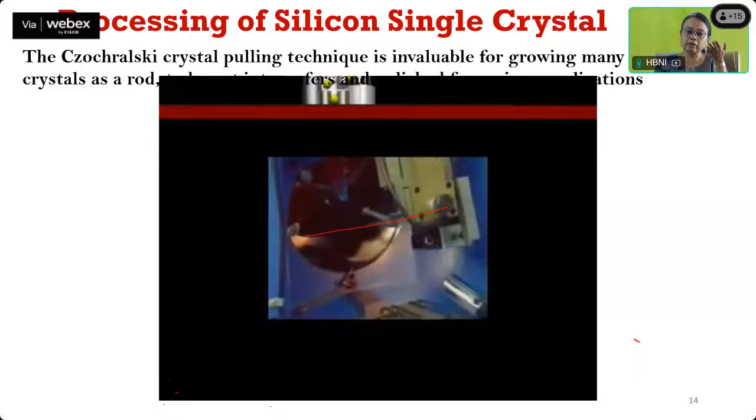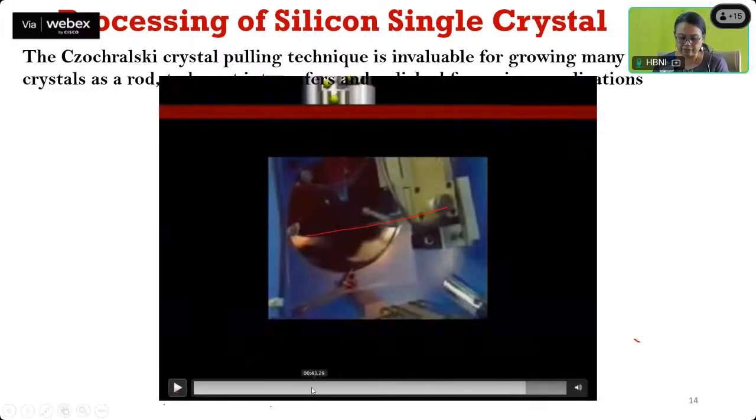Also it depends on the kind of dopants there. If any impurity or dopant has a good segregation coefficient, it remains dissolved in the melt and you get pure solid. But there can be impurities which have a similar dissolving coefficient in the solid phase and in the liquid phase. Those you cannot purify using crystal growth. Okay, thank you. So I will come back again to this, because you must not have seen everything.